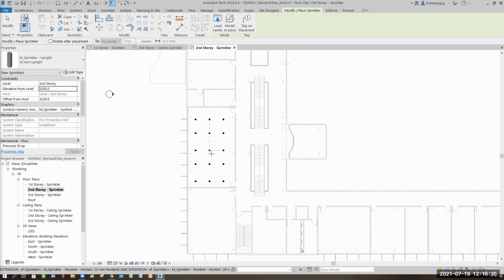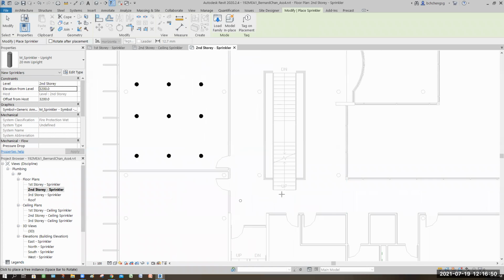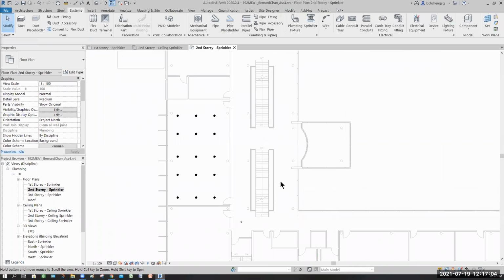So between this 2.6 and 3.2, we have 600 mm to play with. So later when the main pipe comes out, you need to gauge the height later on. So take note. From here, assuming that, look at this line and the center line. Estimate that this is somewhere here. This is one of the sprinkler heads at 3.2. After that, you array.